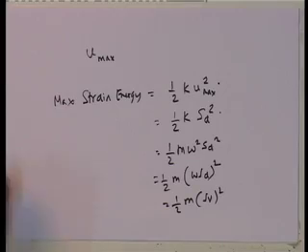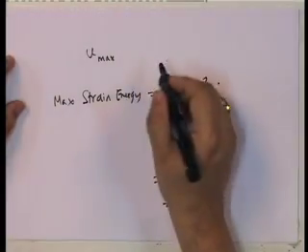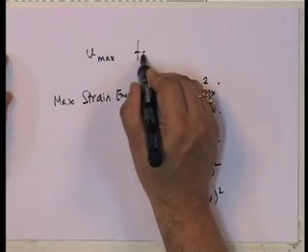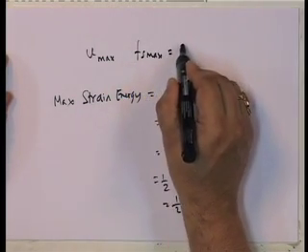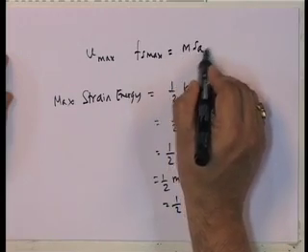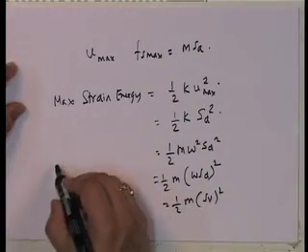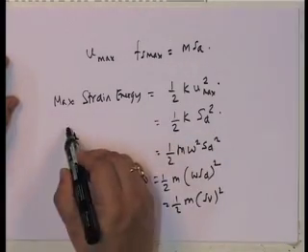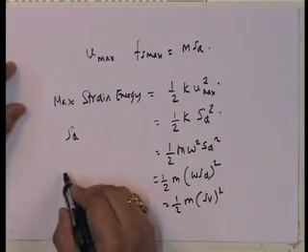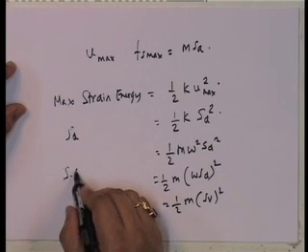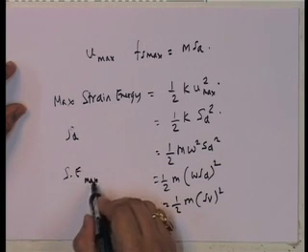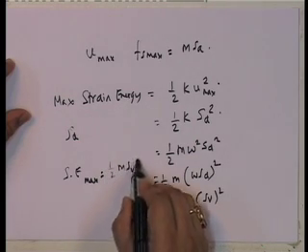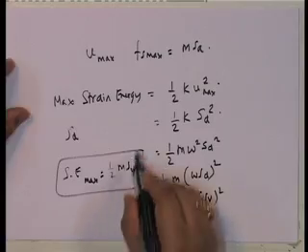So, in other words, what is S A required for? Because F S max is equal to m into S A. What is S v? S d of course is directly, I know what S d is, the maximum deformation, and the maximum strain energy is equal to half m S v squared.